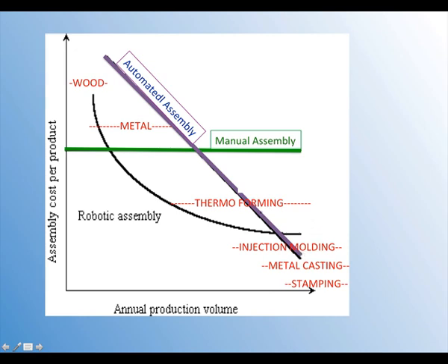Thermoforming, your operations are 2 to 5 minutes typically. It's a slower process, but your investments are much lower. Thermoforming works great for volumes that are between 1,000 and 10,000 parts. And below that, you're probably talking about working with wood and metal, and mostly manual assembly or CNC and laser cut, robotic programmed cuts.